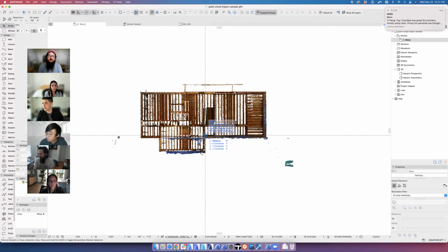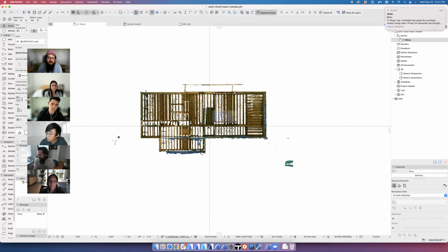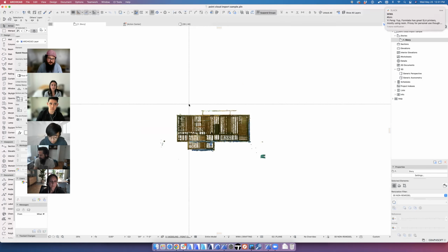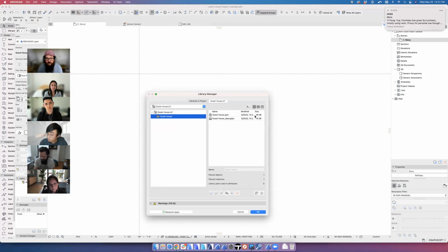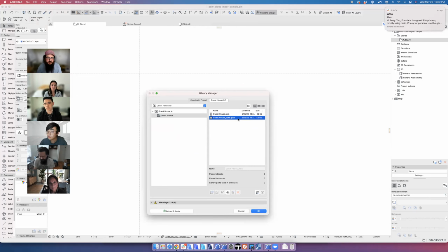And then when we're done with these point clouds, if you are checking them in your main working file, make sure that we're not storing them in there. We talked at a lunch and learn recently about general file maintenance management, sort of self audits. Keeping the file lean is important for maintaining the workability of our Archicad files. These objects are big. If we look at the converted object here, we've got like 1.6 gigs of data just with this macro file alone. So this file is 1.6 gigabytes bigger because we're storing that in there. Let's not bloat these files up any more than they need to be.